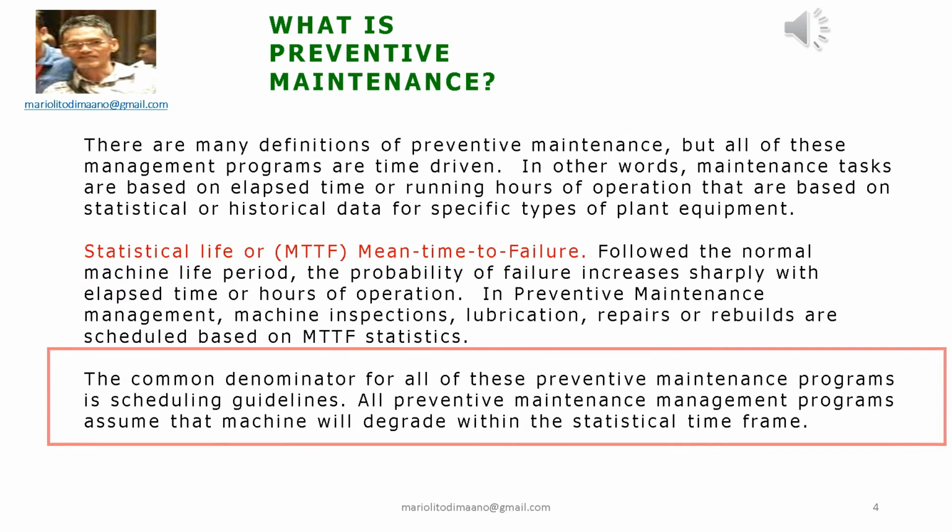What is preventive maintenance? There are many definitions of preventive maintenance, but all of these management programs are time-driven. In other words, maintenance tasks are based on elapsed time or running hours of operation that are based on statistical or historical data for specific types of plant equipment. Statistical life, or MTTF, mean time to failure, follows the normal machine life period.